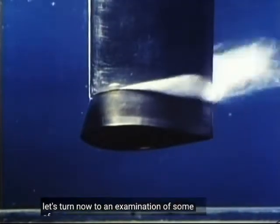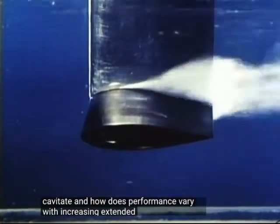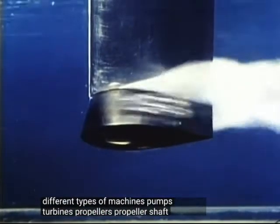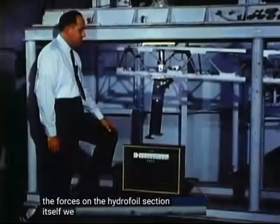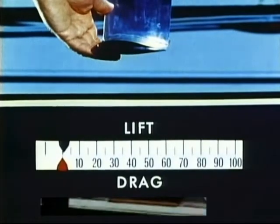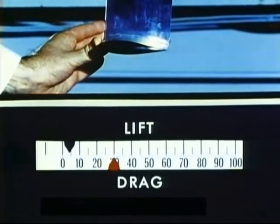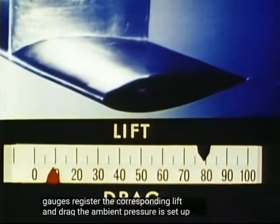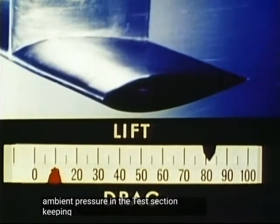Let's turn now to an examination of some of the effects associated with cavitation and cavitating flows. What happens to a machine when it begins to cavitate, and how does performance vary with increasing extent of cavitation? Since hydrofoil sections make up so many different types of machines, pumps, turbines, propellers, propeller shaft struts, mixers, we can illustrate what happens to all such machines by studying the forces on the hydrofoil section itself. We have suspended the first hydrofoil model from force gauges, which show us lift and drag on these scales. The flow speed is constant, and the gauges register the corresponding lift and drag. The ambient pressure is set at a level well above that at which cavitation can occur. We are going to induce cavitation by decreasing the ambient pressure in the test section, keeping the speed constant.